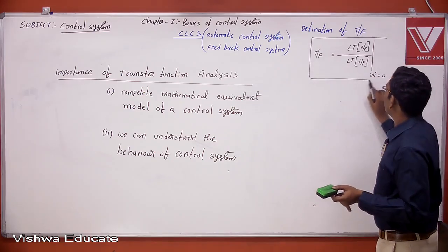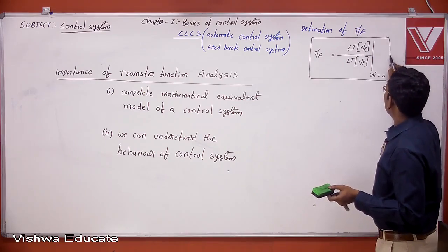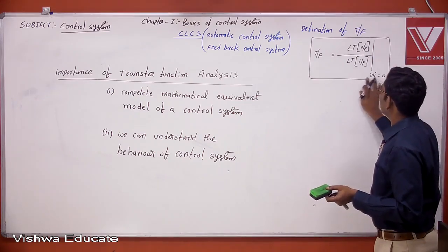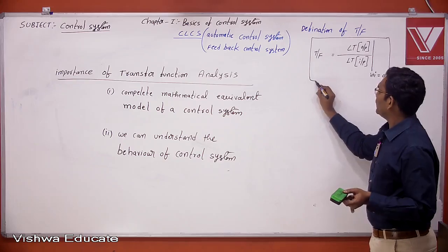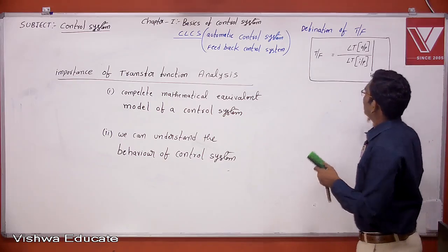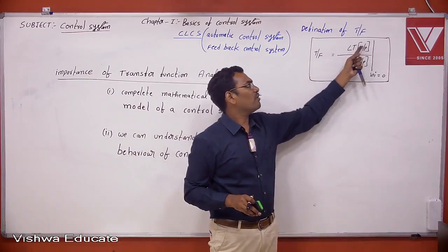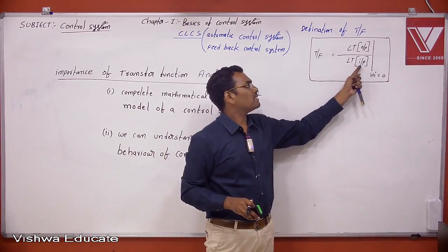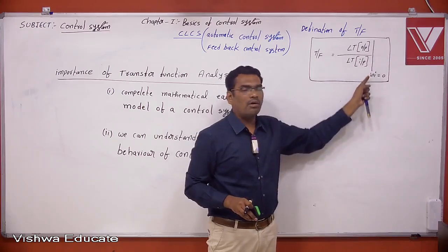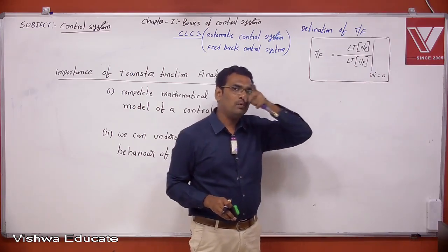What is the definition of transfer function? For a linear time invariant system, once again I am saying, the transfer function is defined as the Laplace transformation of output to the Laplace transformation of input, with all initial conditions equal to 0.